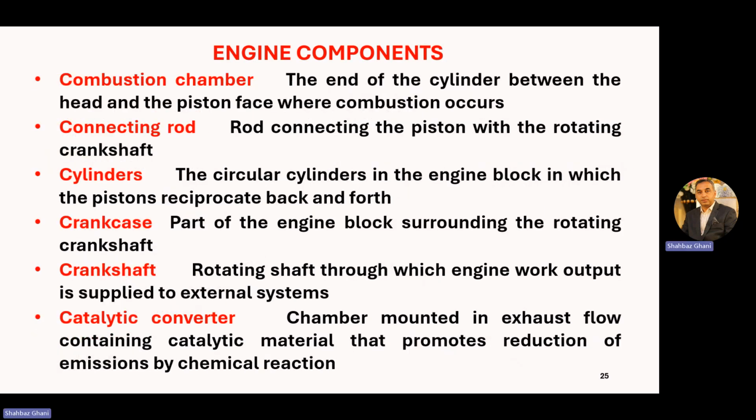Now, combustion chamber. The end of the cylinder between the head and the piston face where the combustion occurs. When your piston reaches TDC, the only volume space which we have is the clearance volume, and in that clearance volume the combustion ignition starts and then leads to the combustion. That area or space is known as the combustion chamber.